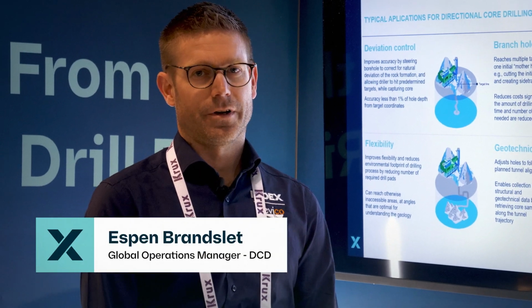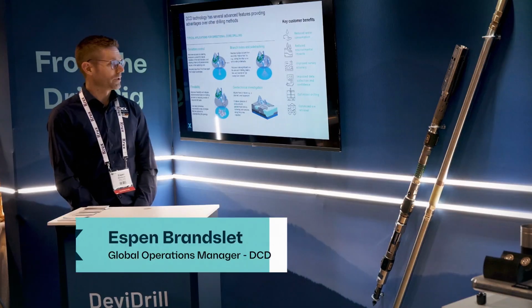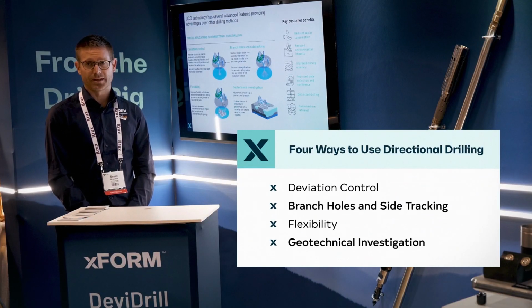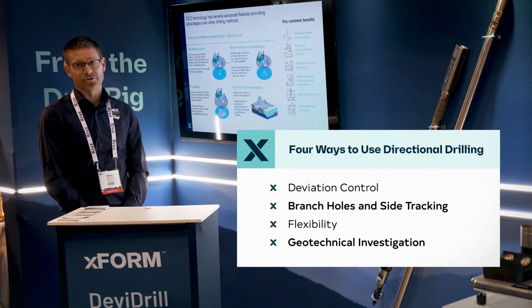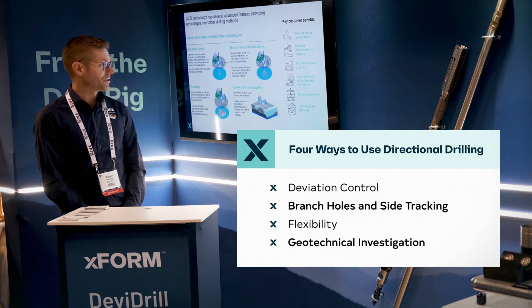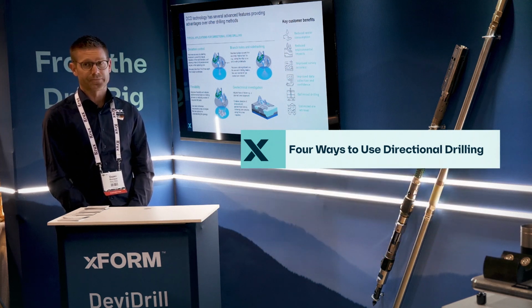There are many ways to use directional drilling. We define 4 applications where directional drilling is mainly used. That is deviation control, branch holes and side tracking, flexibility within the exploration, and geotechnical investigation.